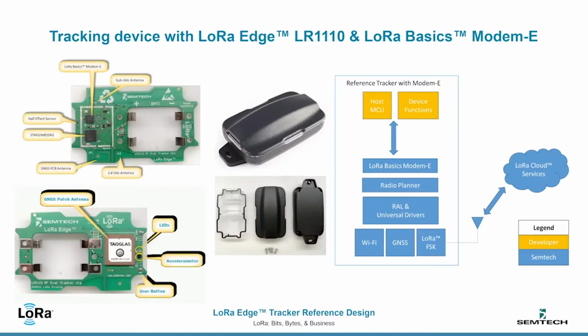It interfaces to the LoRa Basics Modem E firmware, and the Basics Modem E firmware is responsible for handling all of the cloud services interface, including a LoRaWAN stack. And it also handles Wi-Fi, GNSS scanning, in addition to all of the radio planning and concentration for the LoRa